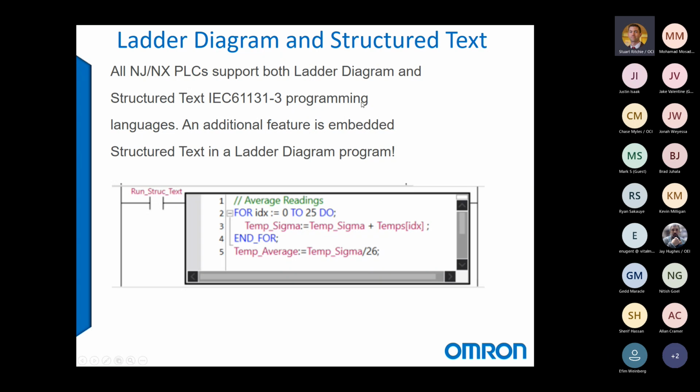Now, Sysmac does ladder logic, ladder diagram, and structured text. Now, there's a nice feature in Sysmac where we can have the best of both worlds and do what's called embedded structured text. So you can see in the picture here, it's on a ladder rung, but it's executing structured text instructions.